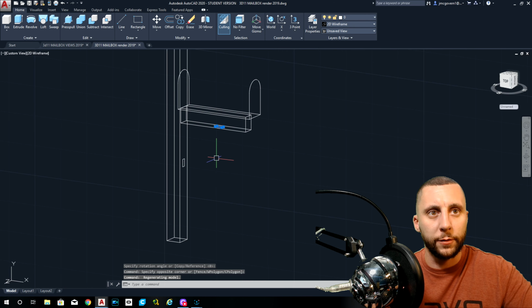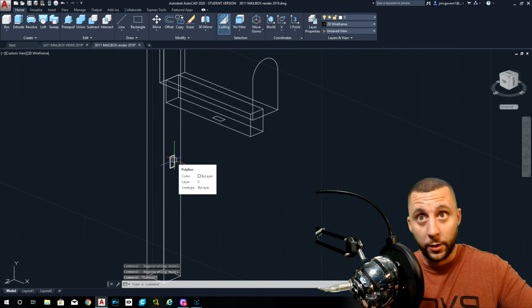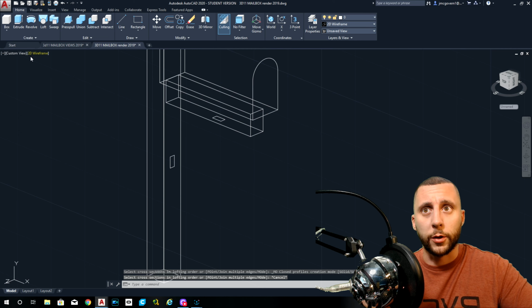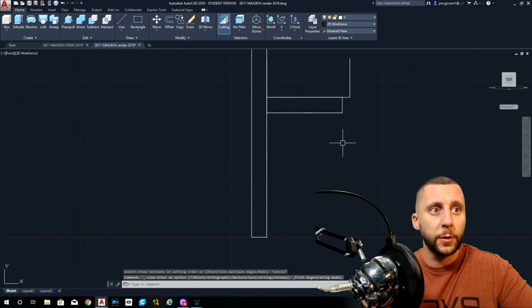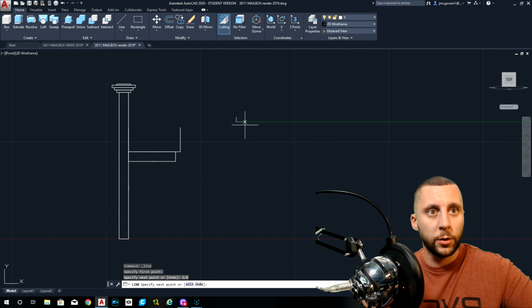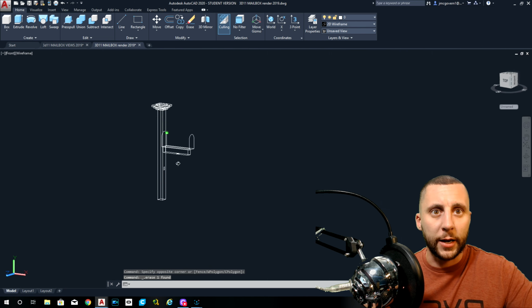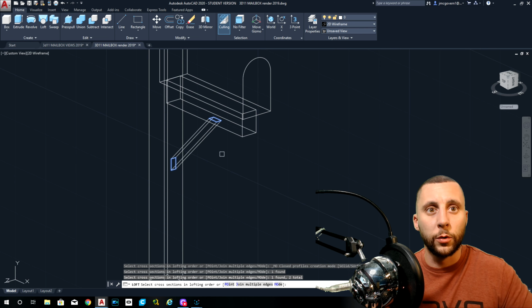Going back to a 3D view, I now have two of them, one underneath and one on that right side there. If I use the loft tool, there's other ways to do this too. You could have drawn the front profile of it out here. Let's see, are we on the front? Okay, you could have gone 1/8, draw on the diagonal, 1/8, draw on the diagonal. You could have done that as well, join those four together and extrude it, but I kind of like doing it this way. I like using loft. Loft, 1, 2, enter, enter.